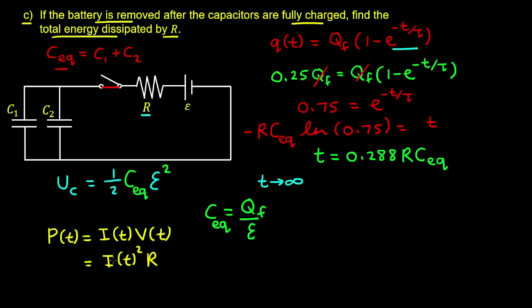So here we applied Ohm's law because the resistor is an ohmic circuit element. And recall that the differential equation for a discharging capacitor had the following solution, which was the initial charge on the capacitor by e to the minus t on tau, being the time constant.